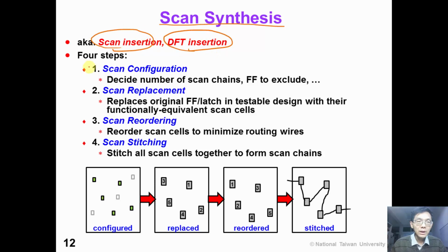Scan synthesis can be broken down into 4 small steps. In the first step, scan configuration, the designer can decide the number of scan chains, and the designer can also specify which flip-flop to exclude from our scan chain.